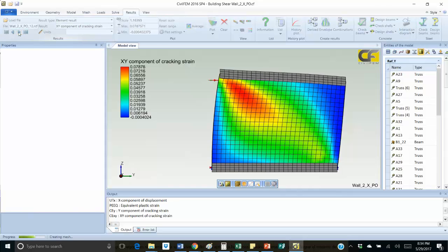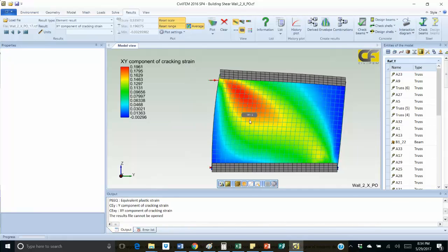Okay, we're going to this step. So now you can see the order of the magnitude. We're going at 0.14 as a strain, 0.16. Okay, so basically, if you go further, you can make an analysis where you can take the structure as if you were doing a pushover analysis, where you can evaluate the cracking, then you can evaluate the yielding of the steel, and once we get to that point, that well, we didn't do that here, we can evaluate the plastic equivalent deformation of the bars.